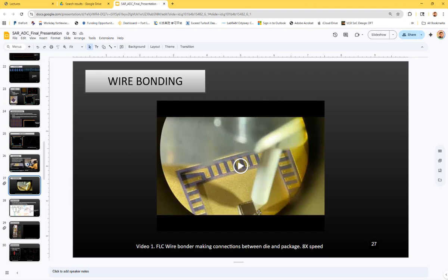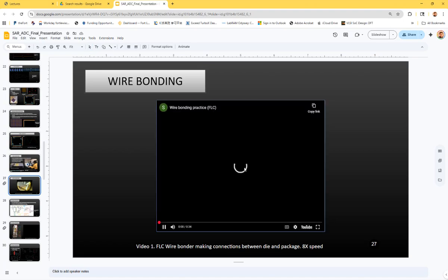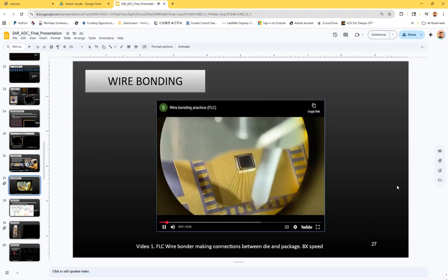So it's basically just this tip, and when you bond it, give a pressure on the top and just smear that gold wire onto these pads. You can see these little dots are smeared wire, connection joints. You couldn't see the wire because they are so thin, right? And the process of bonding is like this.